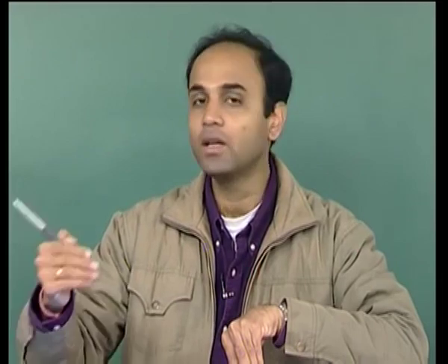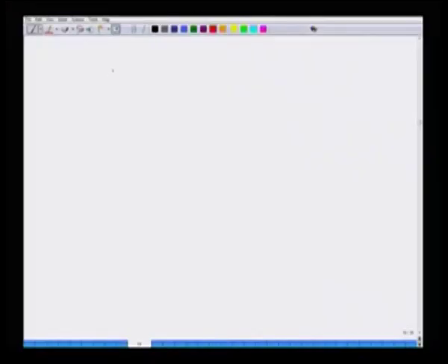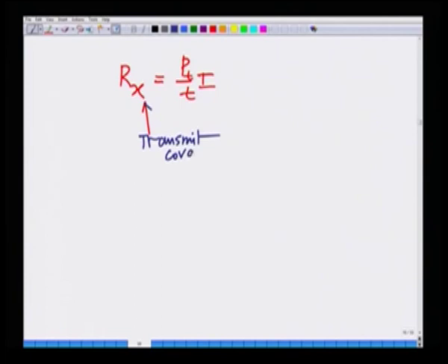Now, what I am going to assume here is a simple transmit covariance structure. I am going to assume that whatever power P is available at the transmitter is distributed uniformly across all the transmit antennas. That is, each transmit antenna is allocated a power P over T. Hence, my transmit covariance R x equals P T over T times I. This is the transmit covariance.